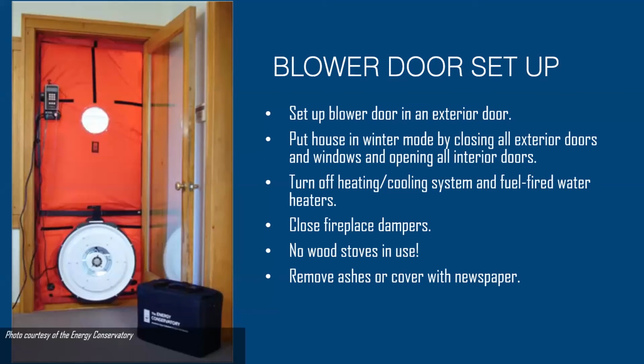Let's look at the steps for setting up the house to conduct a blower door test. Make sure you start by putting the blower door in an exterior door. It's important to put the house in winter mode, which means closing all the exterior doors and windows and opening all the interior doors. It's important to turn off the heating and cooling system as well as the water heater, particularly a gas-fired water heater. We typically put them into vacation mode or pilot mode.